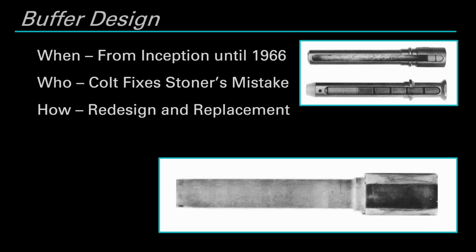This is because one of the most common reported issues was this light strike bolt bounce issue. While in the grand scheme of jams, it's a pretty easy one to clear, you simply have to rack the rifle. And the fact that it only affected full auto fire meant that there's only going to be a subset of situations when it was going to matter in the first place. The issue was fairly endemic, and it was something that needed to be addressed.